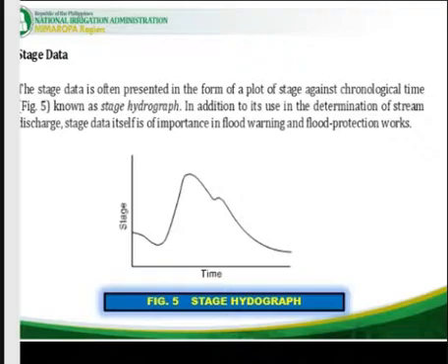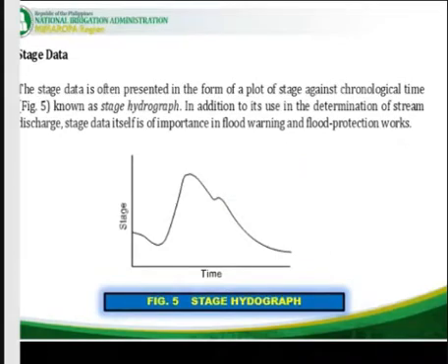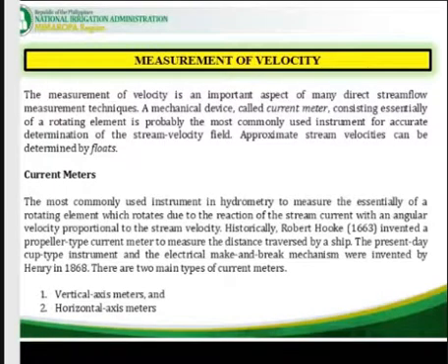Stage data. The stage data is often presented in the form of a plot of stage against chronological time, known as a stage hydrograph. In addition to its use in determination of stream discharge, stage data itself is of importance in flood warning and flood protection works. Okay,